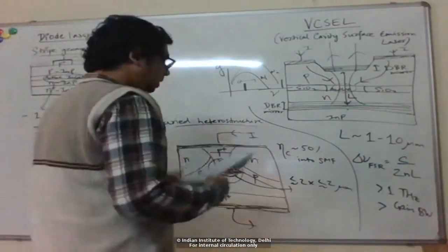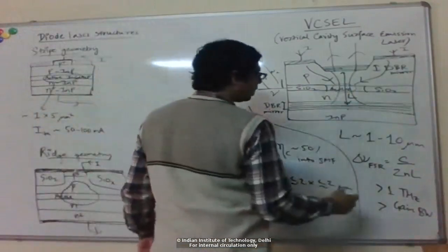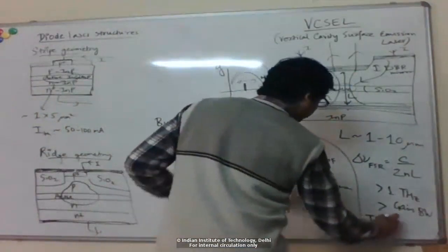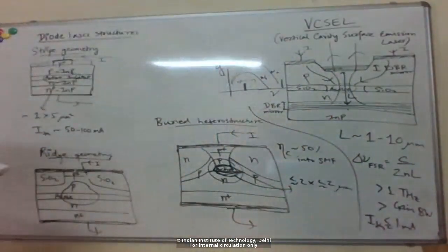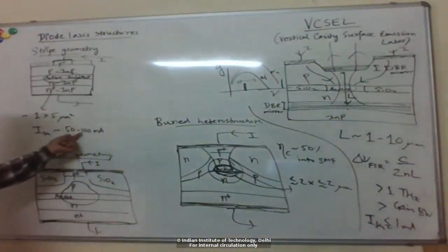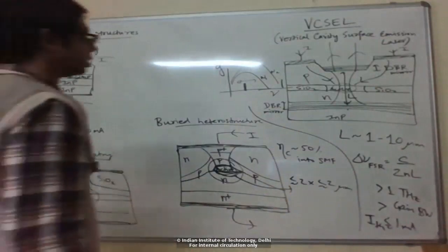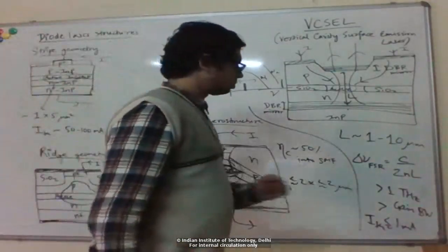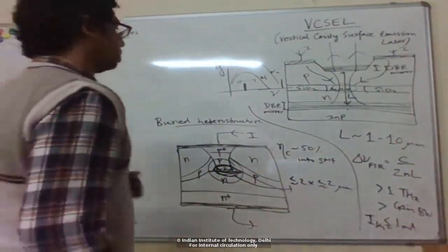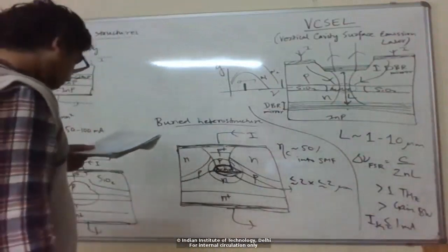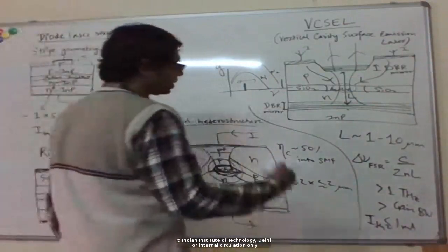single amplitude laser, right? And not only that, because the active region is so small, typical threshold currents here can be brought down to like a milliamp or so. You can see it's much smaller, almost 2 orders of magnitude smaller than typical diode laser structures. So for these VCSELs you can operate them at very low currents, or low DC powers, basically. And these can also give you very high modulation bandwidths.